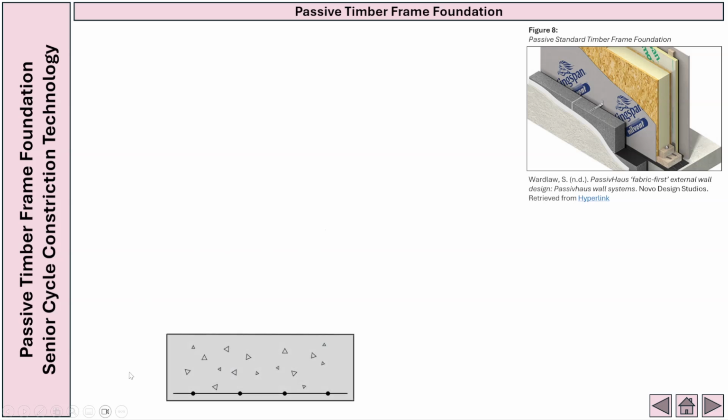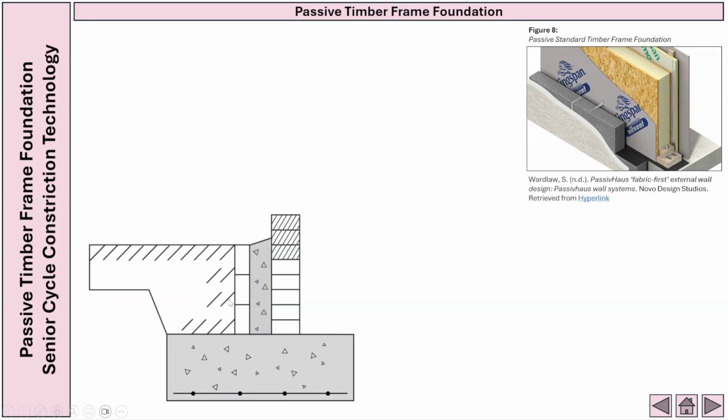The first thing you're going to draw is your reinforced concrete foundation, and this is measured in at 1260 by 420. The next thing we're going to do is start drawing our external leaf and our internal leaf. You're going to see that in the foundation we've got 3 vertical blocks, and then on the right hand side we're going to start off with 1, 2, 3, 4, 5 horizontal blocks, followed by 1, 2, 3 insulated lightweight blocks. Then we're going to have our concrete infill, and on the left side we're going to draw in our ground, and on the right side we're going to draw in our hardcore.